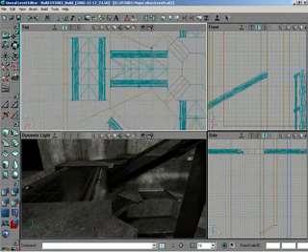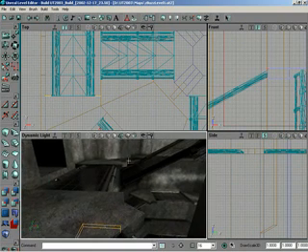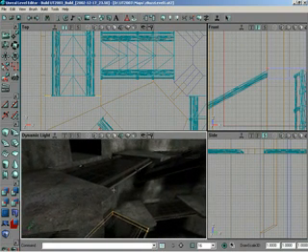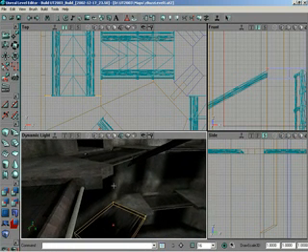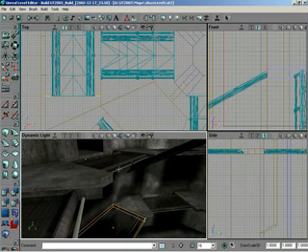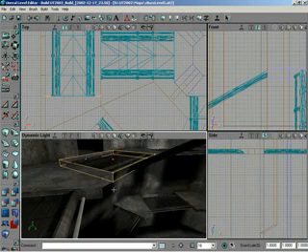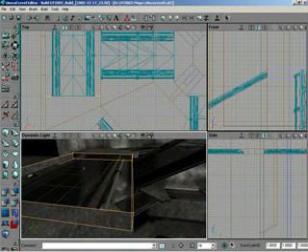Okay, let me take a look at that. There's the brush that we initially subtracted out. Well, the one below it. The one below it. All right, here's what I was talking about. The wireframe perspective can get very useful here because I can't tell. We have two brushes shaped exactly alike, but on top of each other, so it's hard to grab one from the top. Whereas if I go from a perspective, I can easily see that I want that one. Then I can go back to a shaded view. And so we see that that's what we subtracted out, and we see we subtracted that piece out.